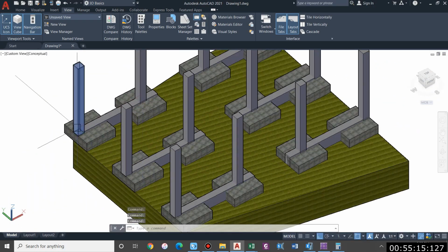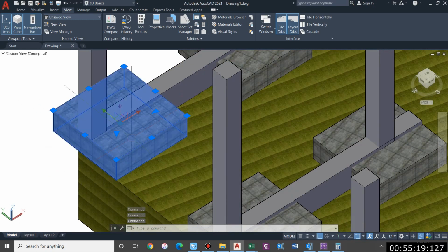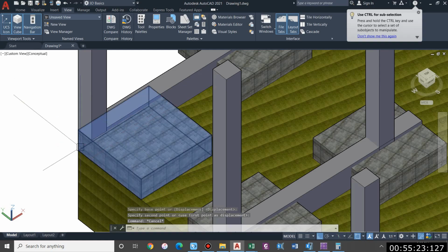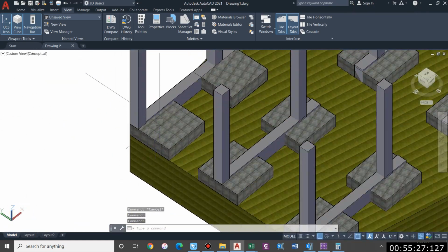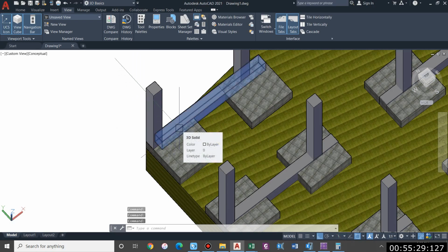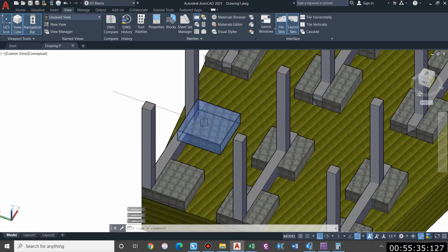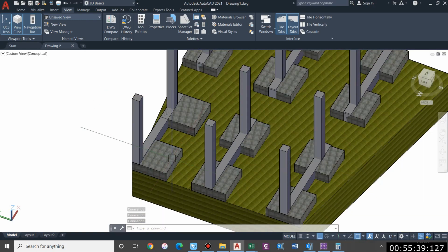So what I had to do is provide a mat footing, because a strap footing cannot be provided in such a way. The simple idea is to distribute the pressure throughout the area available, and for such a case both of the footings would be eccentric and there is no chance of this footing passing the bearing check.